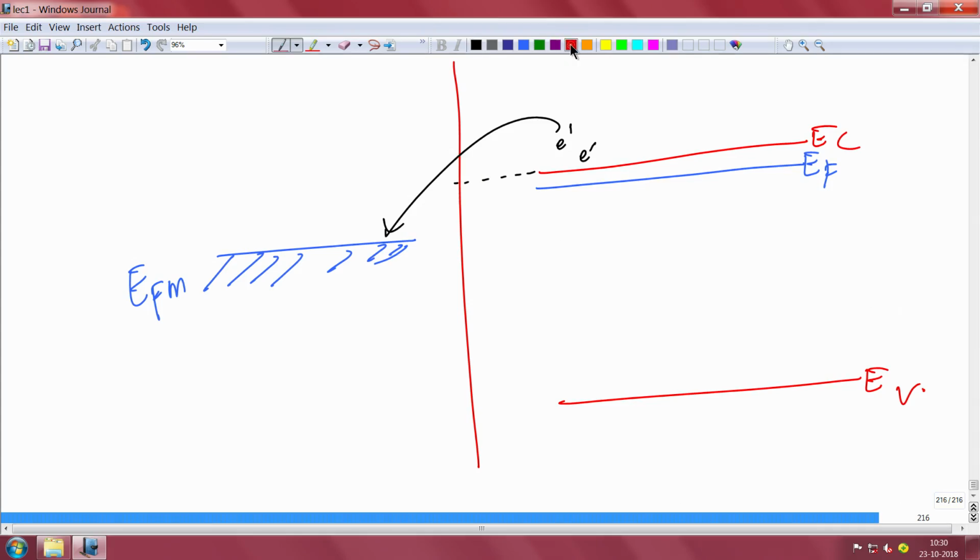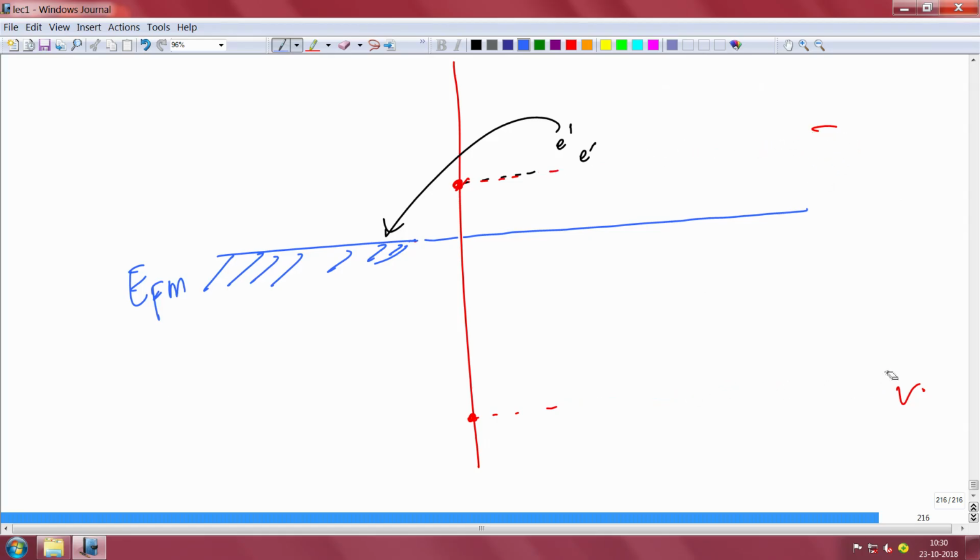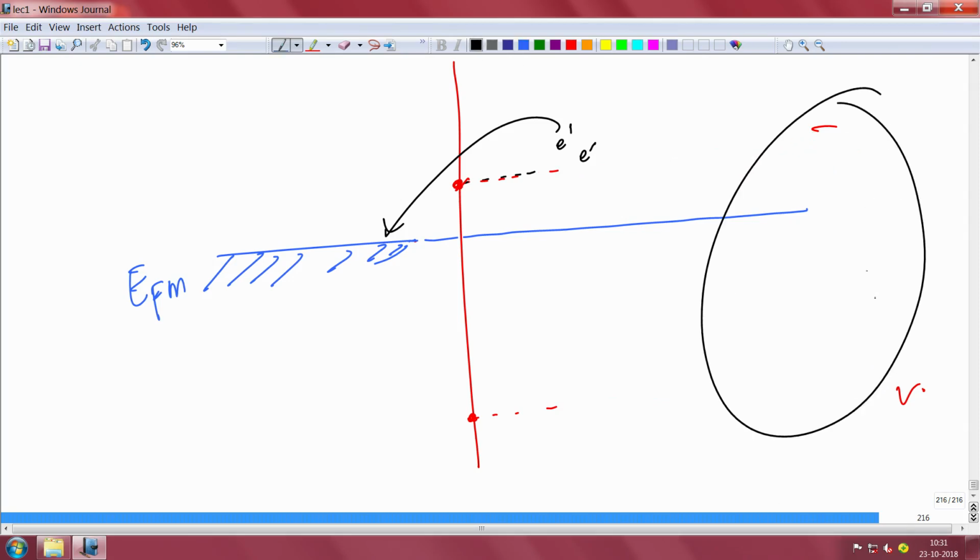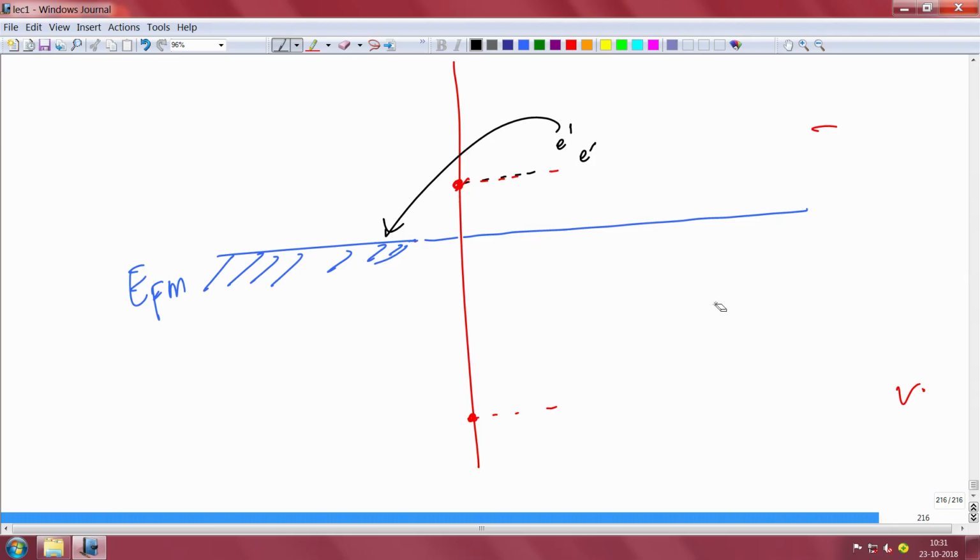the way to draw it is that you imagine this point, the conduction band point here, to be fixed. Imagine that this point is fixed here, and now you move the whole thing down, by keeping that fixed point and keeping the Fermi level down. So, what will happen is that eventually the Fermi level, which is the blue color, will have to be equal everywhere. So, this Fermi level has come down here. But far away from the junction, what will happen is that your semiconductor is not changing. So, the conduction band and Fermi level difference has to remain constant because the doping is uniform in the semiconductor.